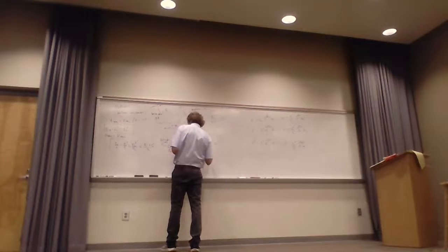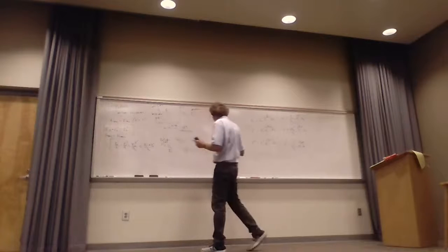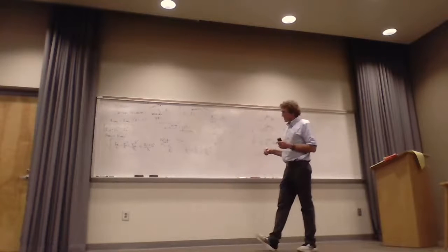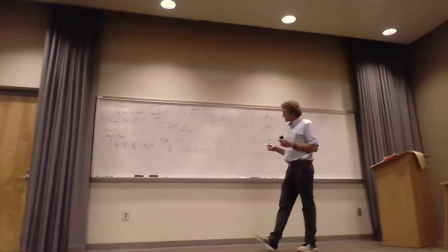is equal to 1 plus the reflection coefficient over eta 2. And the only thing I've done there is divide top and bottom on that first equation by E naught incident, and replace the ratio of E naught reflected to E naught incident by the reflection coefficient.